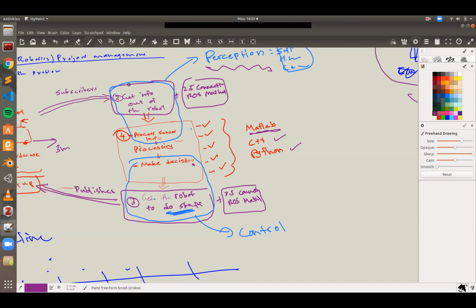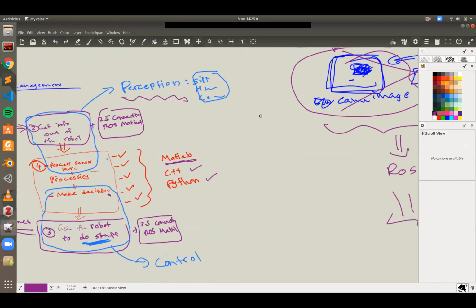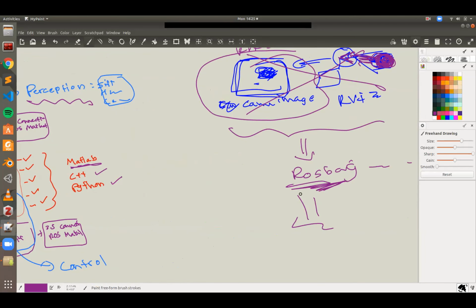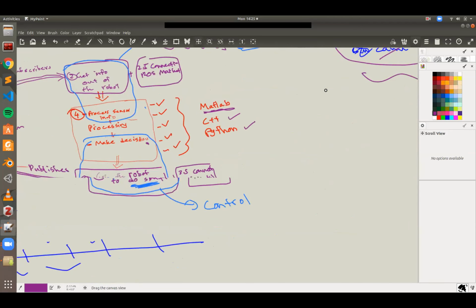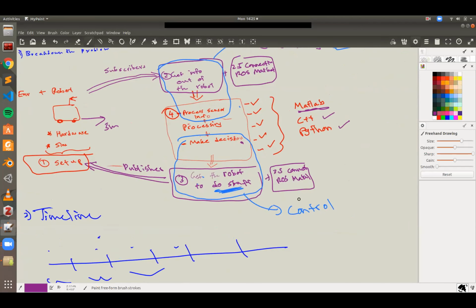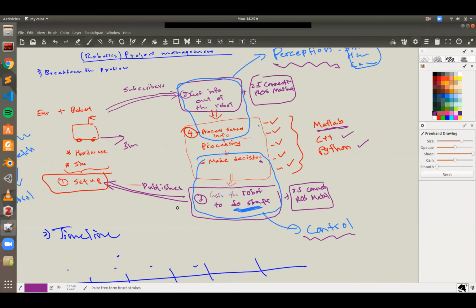So for example, in this part, you don't always have to run your Gazebo simulation, because it'll be annoying, I get it, especially when you're debugging code, you'll make mistakes and rerun the code over and over again. So in a situation like that, use ROS bags. Obviously, when you're dealing with the control part, you will need your simulation running because you need to publish information, and you can't do that on recorded data because you need to control things and change things.